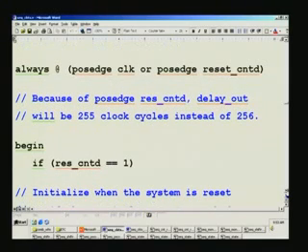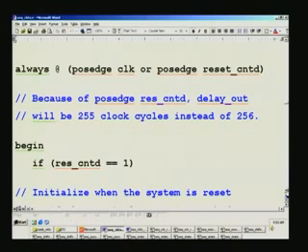Is this a standard way to sense the change in clock, like rising edge or falling edge? No, not necessarily. You can put a flip-flop and realize it straight away, as a clock input, but another rule we will be violating. For all the flip flops, you should have a system clock alone fed to that. So naturally that is not a correct way of RTL coding, right. So the best thing is to realize it in this fashion. After all, clock speeds are very high. We are dealing with 40 megahertz, 50 megahertz. So how does it matter if you are delayed just by a few nanoseconds, right?